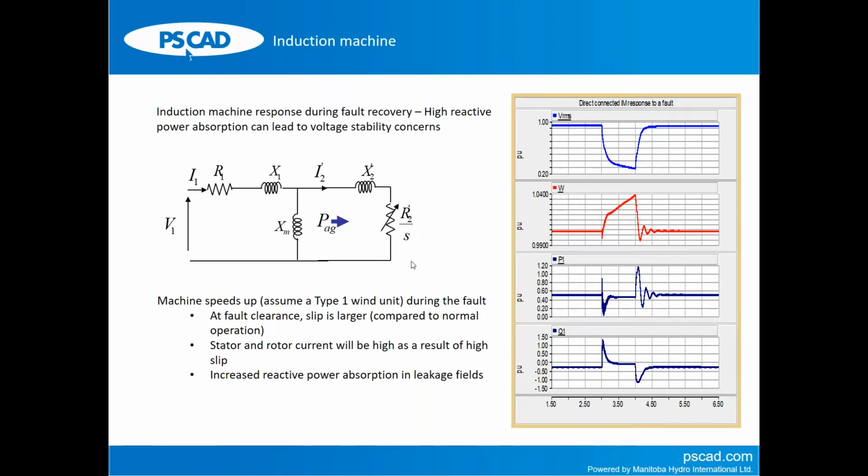So during the acceleration period, until the motor comes to its steady speed, this is low. The starting current could be high, which is not a problem for the motor, but when you start very large motors, high starting currents could create power quality issues because of voltage dips. So I will show you an example. So two common applications: one is AC load representation, motor starting, and also definitely wind turbines.